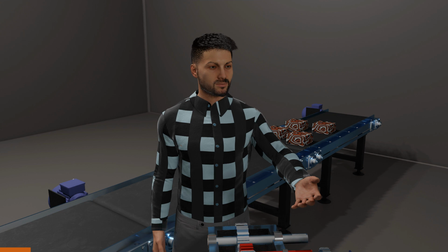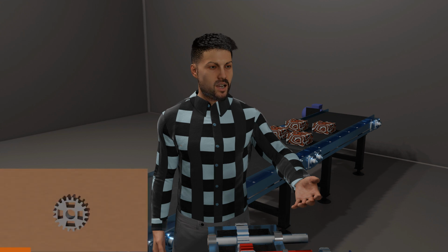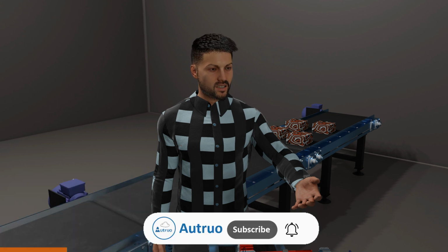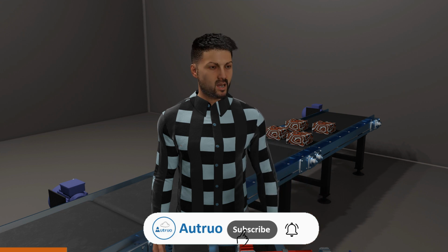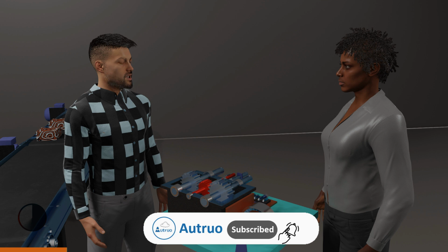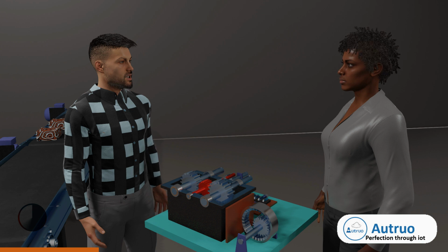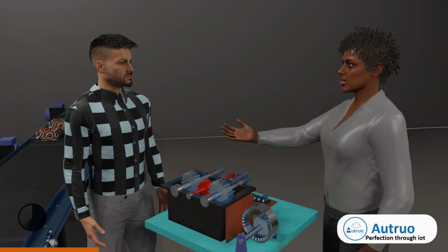That is because the final gearbox is not the final load in the motion chain. Instead, it is used to either change the direction of rotation, or for speed-reducing applications. So having that in mind during gear design will go a long way in saving cost. Examples of such are setup cost and running cost. Again, on the gear design, gears come in two forms, which are gears with hub and hubless gears.